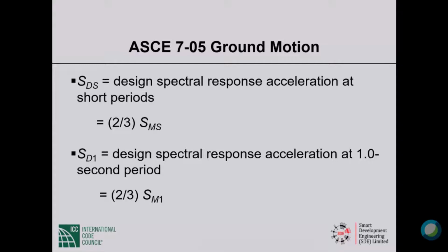What we are saying is that structures designed by the 1973 UBC or subsequent codes are extremely unlikely to collapse on us until earthquake ground motion equals and then exceeds the design earthquake ground motion, which back in the UBC days was 500-year return period ground motion.